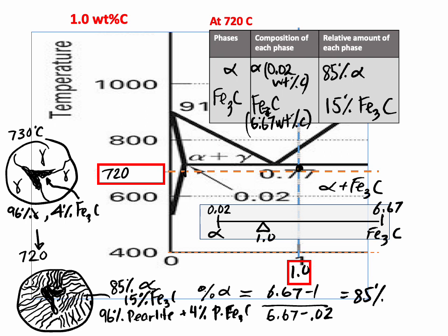All right. The problem with this hypereutectoid steel is that this cementite that I've got here in this bigger area, the pro-eutectoid cementite, is very brittle. And so it's possible that I could form a crack someplace, a knot or a pore or some defect, and it would just travel along the cementite in the ferrite plus the cementite pro-eutectoid. So it's very brittle as a material goes. All right. And that, I think that ends my